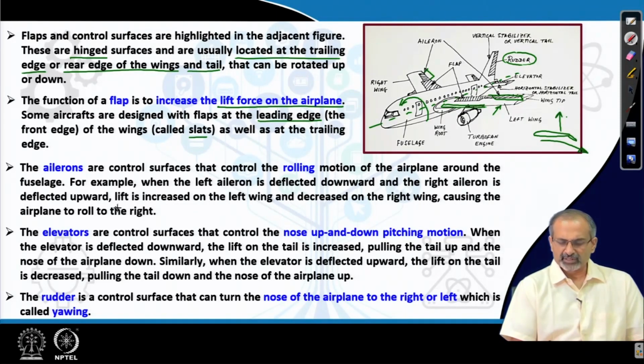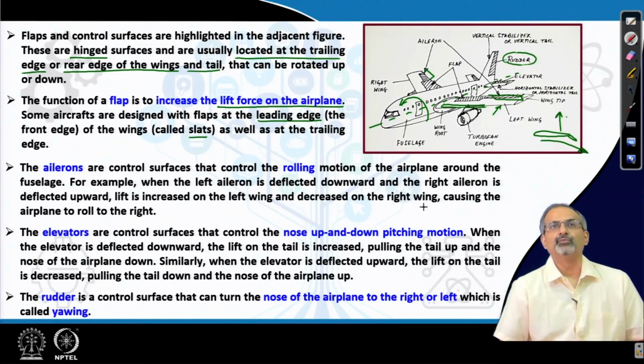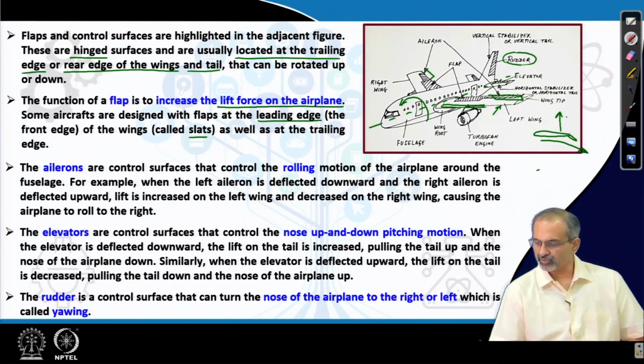And the right aileron, when deflected upwards, will decrease the lift on the right wing, because on the right wing it will be something like this, and therefore, though the main wing section did create a deflection like this, due to the effect of the upward tilted aileron, the net effect of turning will be reduced or maybe like this.